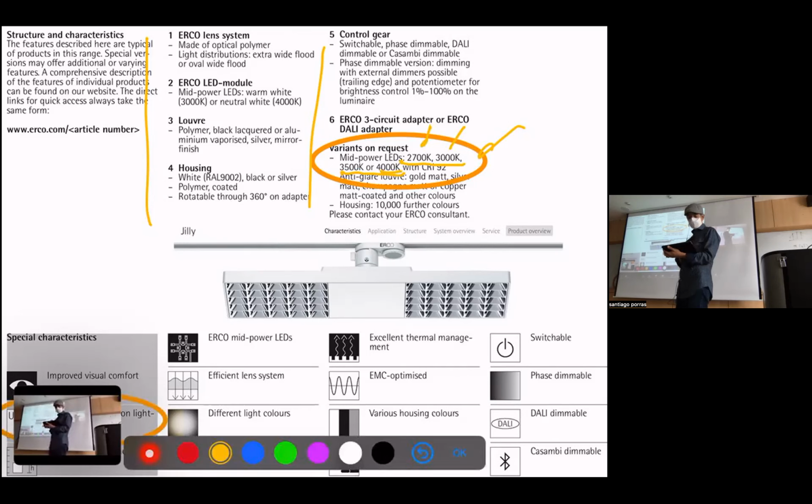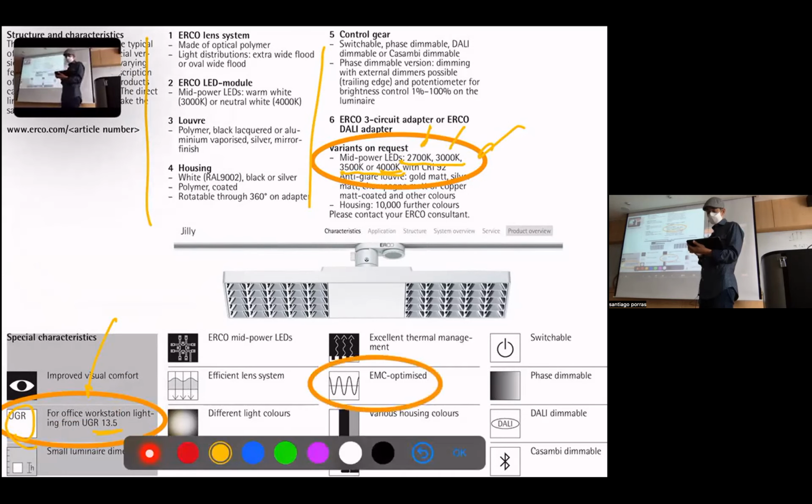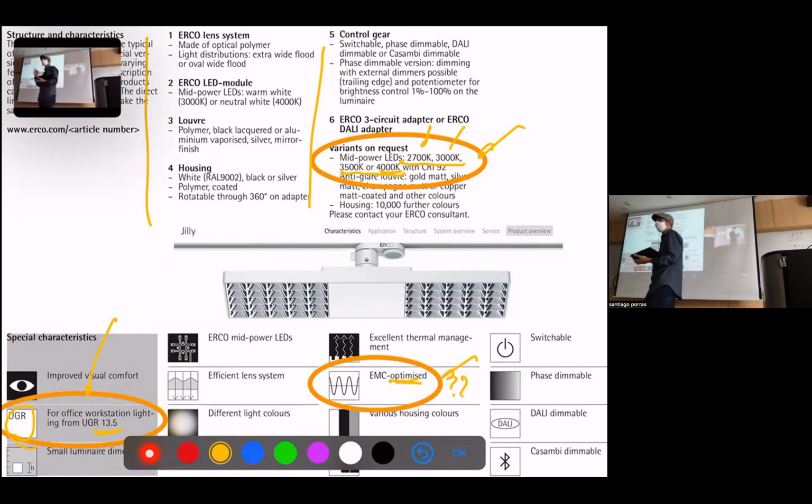For the same lamp. You have the glare index, which is 13.5, which is very close to 10. So we may consider this quite acceptable, right? It's a very good luminaire for general use. Then it is optimized. And this is important because it's LED, right? So they say, okay, optimized, I just become suspicious, right? But it's not certified or proven, just optimized. I see, well, we should check. We should have your engineer check on that, right?